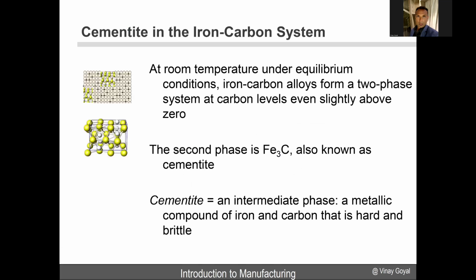So let's look at cementite in the iron-carbon system. At room temperature under equilibrium conditions, iron-carbon alloys form a two-phase system at carbon levels even slightly above zero. The second phase that you may have in this system is Fe3C, also known as cementite.